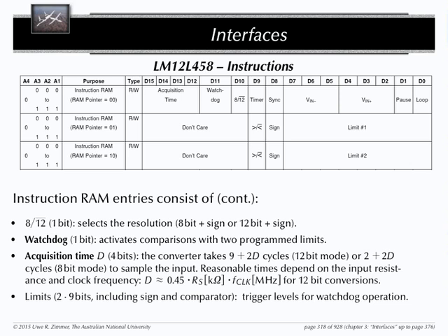It only gives you the watchdog interrupt, and then the CPU can trigger an actual conversion into reading the value in. That's the idea behind it. Saves tons and tons of CPU time. You don't ever read information you don't care about in the first place. You leave this completely offline to this device. Cool.